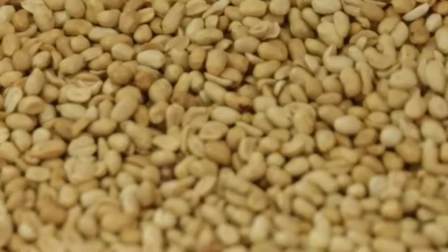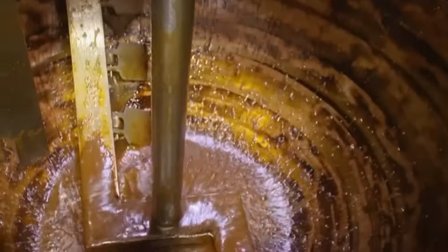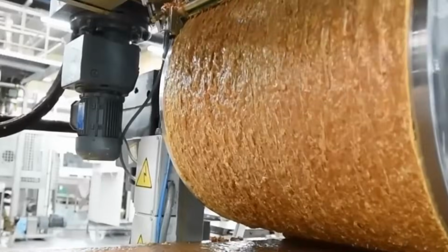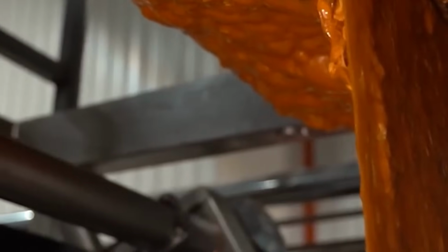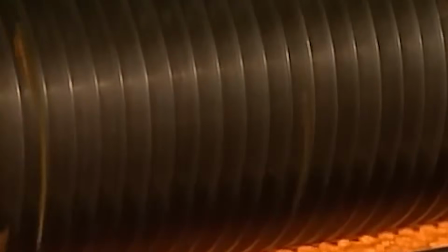The finished peanut butter is stored in jacketed holding tanks equipped with level sensors and recirculation loops to prevent phase separation. The nougat layer is prepared using a continuous aeration system. Corn syrup, sugar, and water are cooked in a steam-jacketed vessel to 120 degrees C and transferred to an aerator, where air is whipped into the syrup, along with milk solids, egg white solids, and stabilizers.